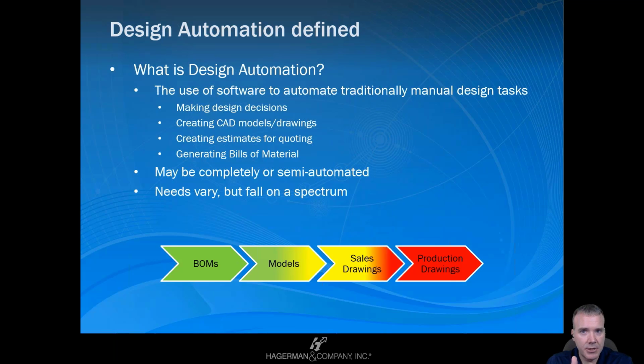That can be a lot easier to produce, that kind of drawing or deliverable, compared to what I would call a production drawing, which is what someone would need to build what you've designed. Production drawings are typically busier. They have more annotations. They have more dimensions. They usually need to be to scale or should be to scale.